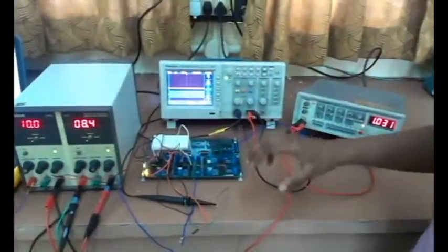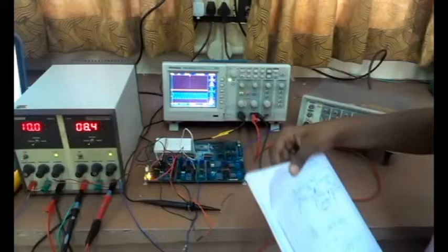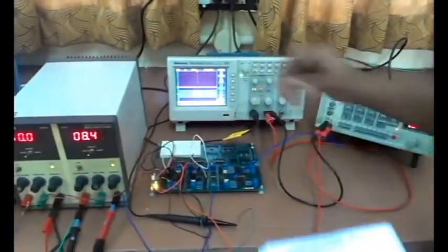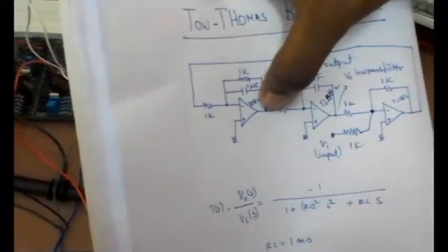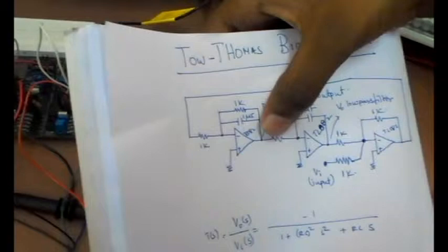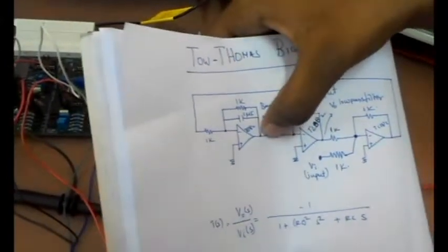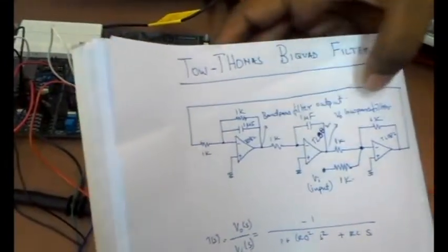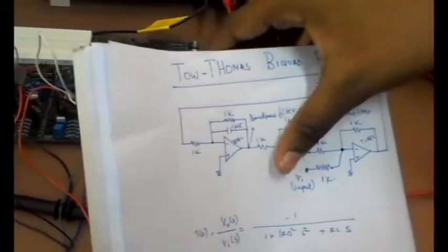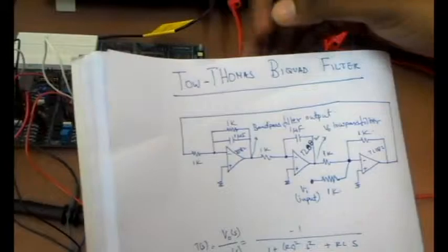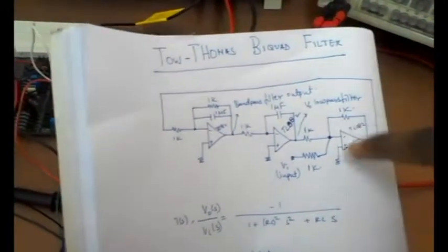The second part of our problem statement is making our filter voltage controlled. Basically we do that by adding a mixer at the output of the band pass filter, that is the input of the low pass filter, and the mixer mixes the input of the low pass filter with a DC value of 1 volt, 5 volt and 8 volt, and we take the corresponding readings for each set.